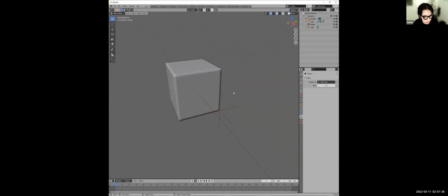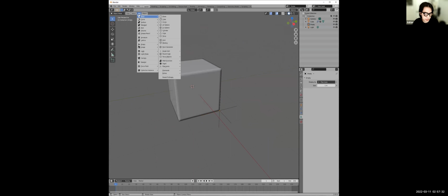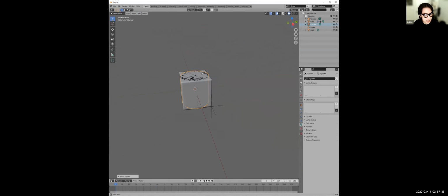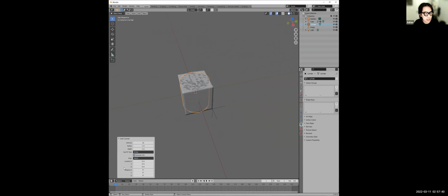The way to do that is we're going to hit add up here, mesh. We're going to make the flagpole or the string for the balloon. Go to cylinder, and we've made a cylinder here. Before we click anything, let's edit these settings. Set the radius to maybe 0.1, the depth to maybe 5. I think that'll be good. Radius 0.1, depth 5, and now we've got a cylinder.